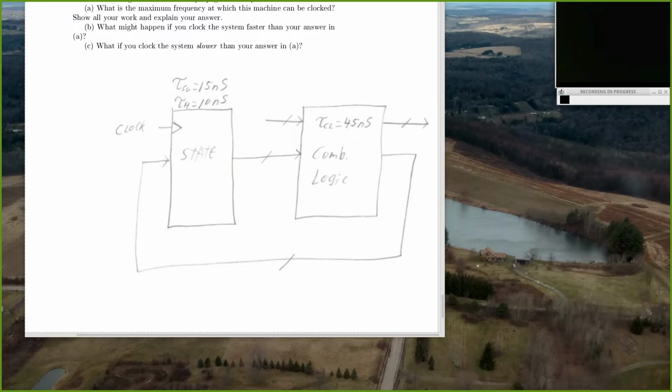So ultimately, you're going to have a circuit with 3 inputs. That's your 3 car sensors and 9 outputs. Those are your 9 lights, 3 per lane. So your system diagram will have 3 arrows going in, 9 arrows coming out. And you want to give names to those that you'll use throughout.